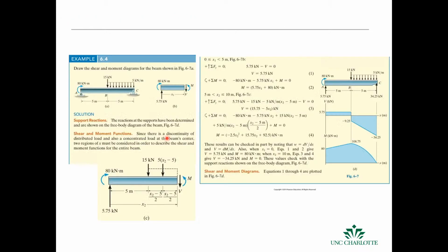This is another example where we can relate the shear and bending moments by summing forces for different slices and different sections, and then we can add them up. So you can see here, when we have this 0 to 5 meters, we have these loading conditions, and then we can get the shear. The moment is the shear times the distance plus the applied moment that we get from solving the statics problem to get our loading conditions at the ends.